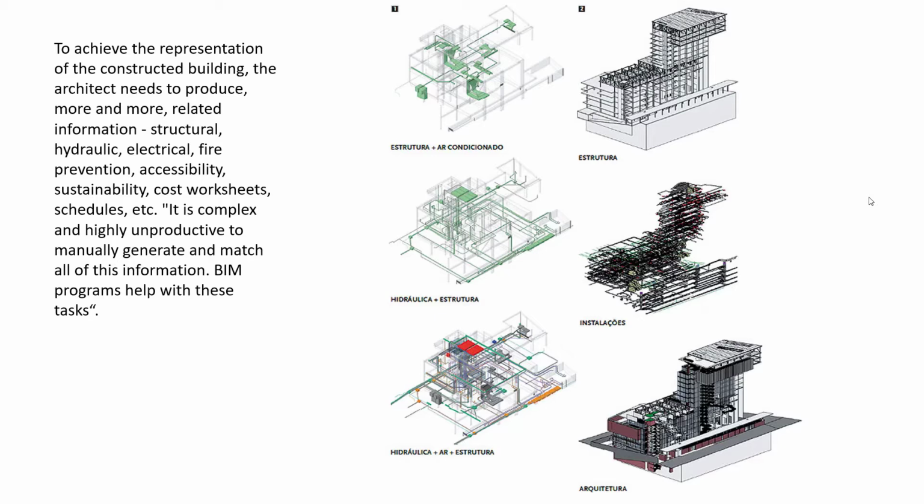So you can receive a file with IFC extension to insert the complementary projects, or you have the option of using a MEP plugin inside Archicad. The structural project is normally calculated in 3D software, so it's easier to import the structure IFC file. The integrated process in 3D is very important to detect collisions among them.